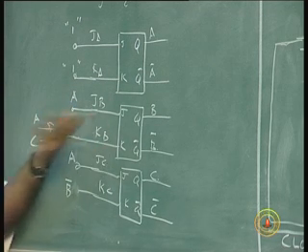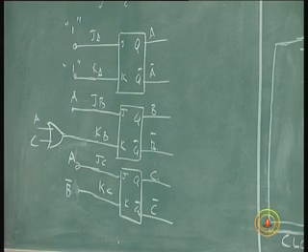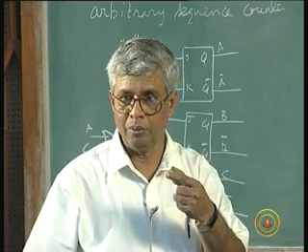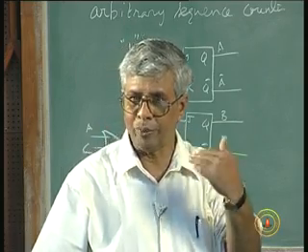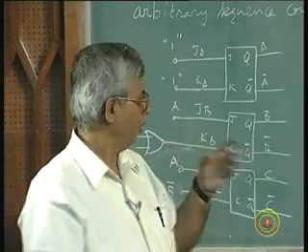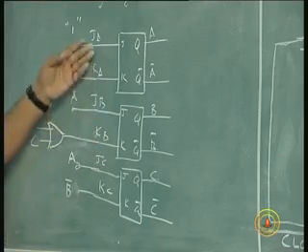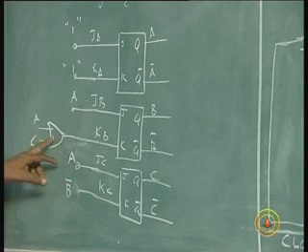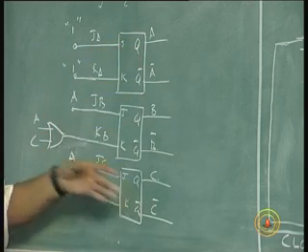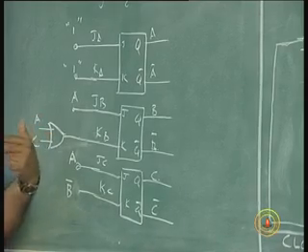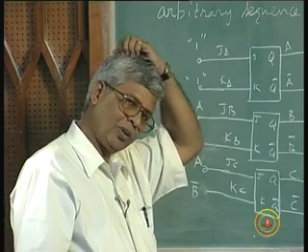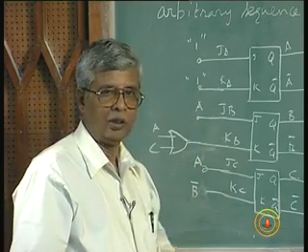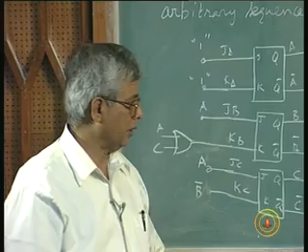So, the logic is, even though we are using 3 flip flops, in the earlier case of D flip flop also we used 3 flip flops, the number of gates used there was more than in this case. Even though there are 2 inputs to each flip flop, the reduction is so much that we are able to use a very small amount of hardware. Only 1 OR gate is extra because all the inverters are available in the flip flops. Only 1 extra 2 input OR gate along with the 3 JK flip flops will suffice and gives you the entire logic.